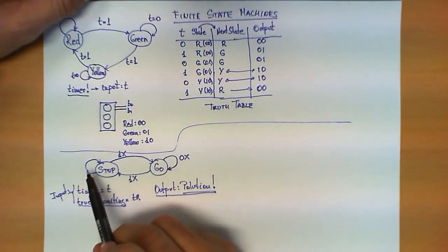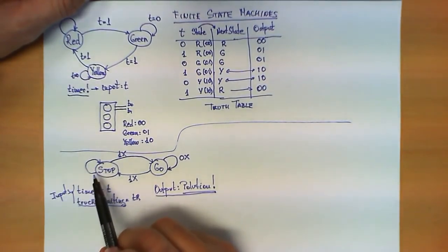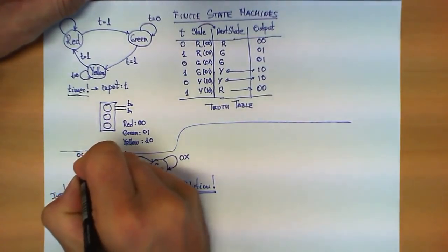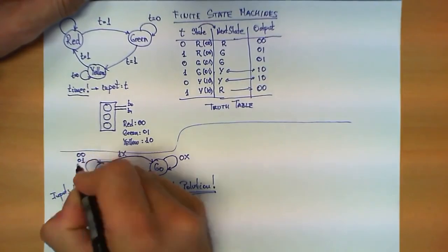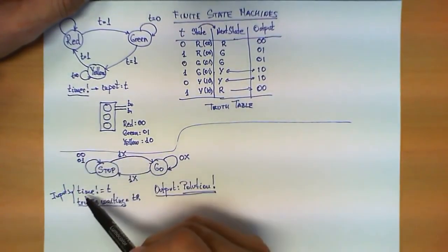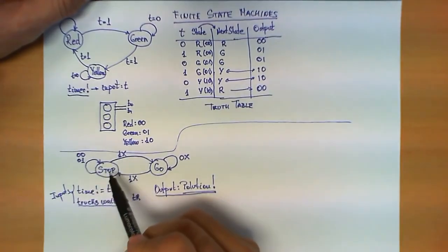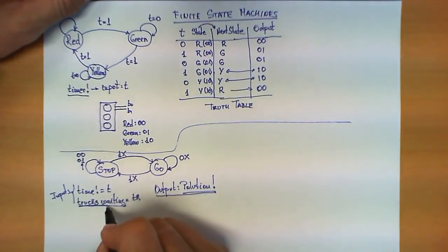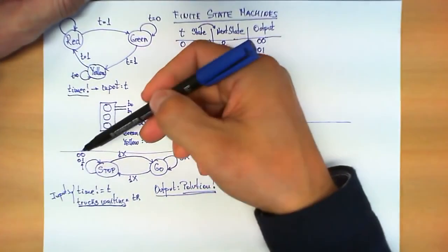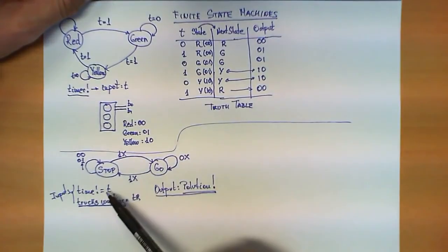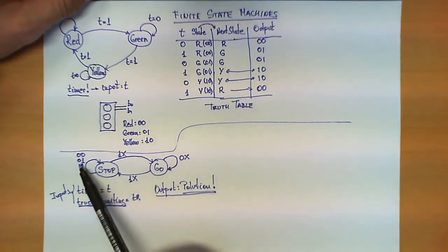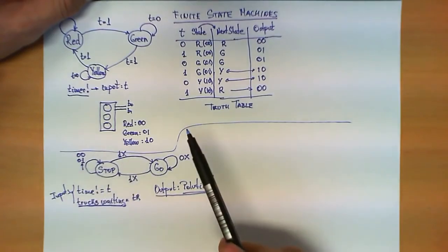Now let's think carefully about this transition over here. Two things can happen producing this transition, which is the value 0, 0 and the value 0, 1. Now we agree that the time hasn't come yet to make a transition, therefore the traffic is waiting, but now looking at this second signal over here, which corresponds to the truck waiting, I have two possible situations. The one above is telling me that the time has not arrived yet, but I don't have any trucks waiting, therefore the pollution should be 0. However, in this situation the pollution signal should be 1.